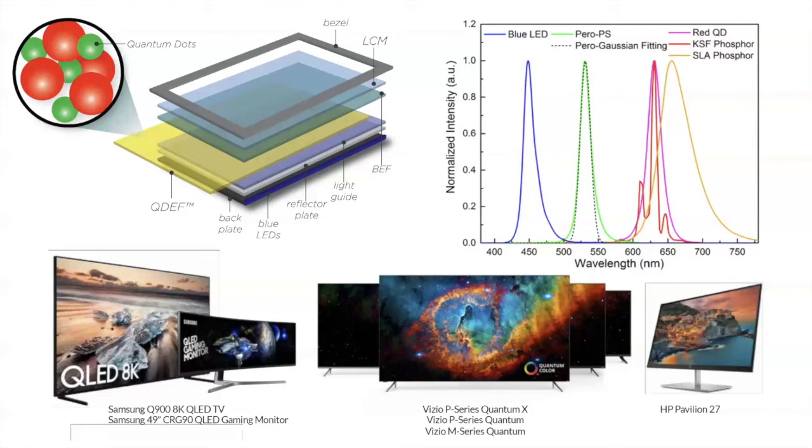This is just a bunch of different shutters that open and close to let out red, green, or blue light. Quantum dots are great for this task because their emission is bright and they absorb light well, but really it's the tunability, the size effect, and also composition, as we'll see in a few slides, that makes the wavelength very flexible. So you can pick whatever emission wavelength you want and get a nice bright luminescence band at that position. The other really valuable thing for these applications is the line width, the narrowness of the peak.